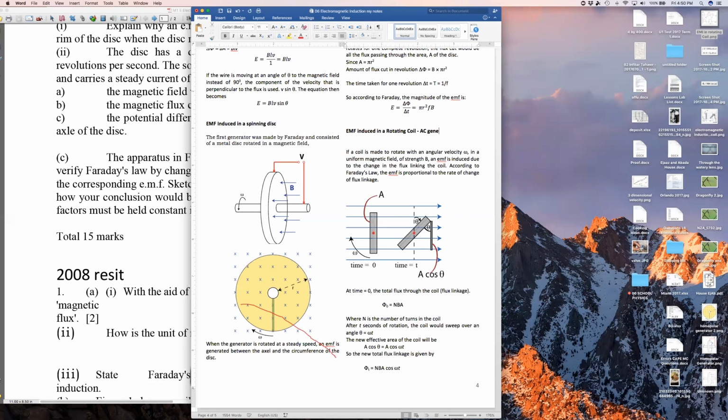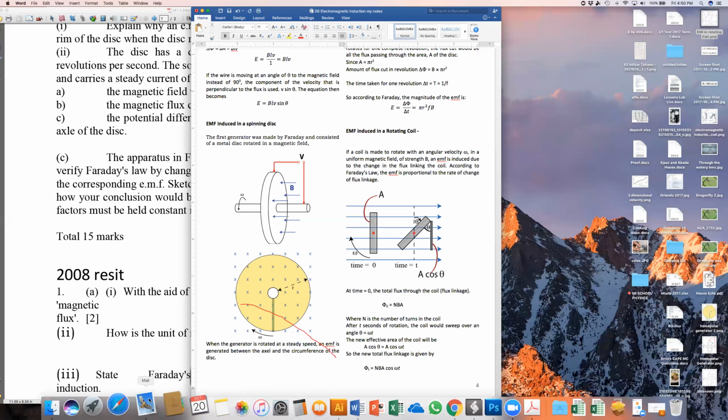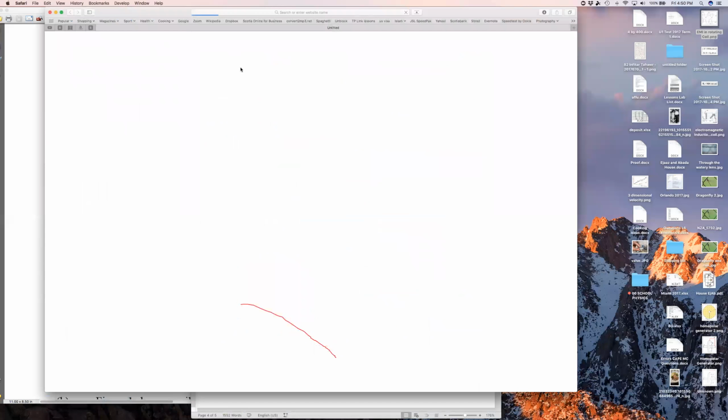It's also the DC generator, because both the AC generator and DC generator do the same thing, except in the DC generator, you have a commutator that rectifies the AC that is being generated. They both generate AC, both the AC and DC generator. Do you know this? Yes or no? Talk to me. Do you all know this? The commutator is the only difference.